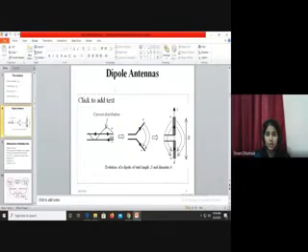Okay. Please draw this diagram also, the dipole antenna, how the length of the antenna is formed. And also the main thing is the current distribution along this length of the antenna, which depends on the length of the wire. Whatever current distribution you see here, like a sine wave, depends on the length of the wire, that means the length of the antenna.